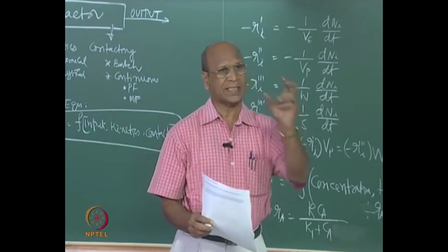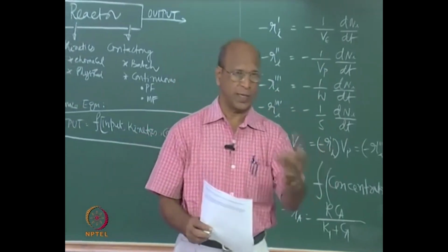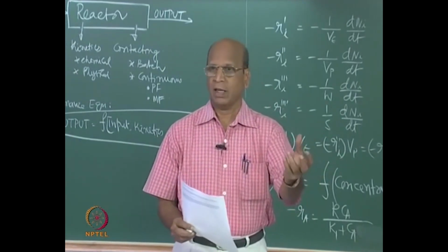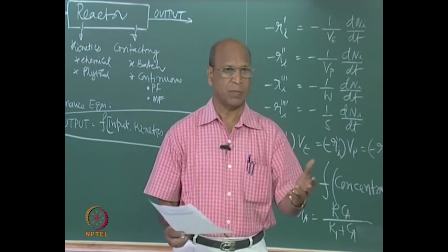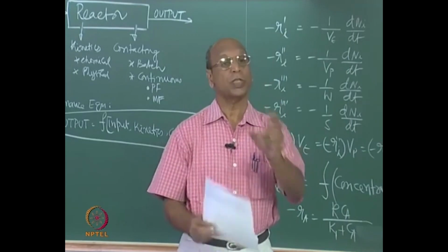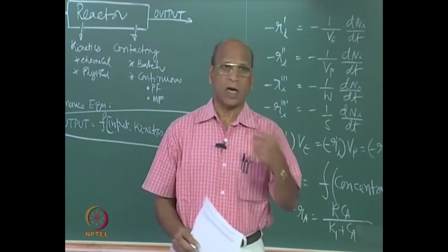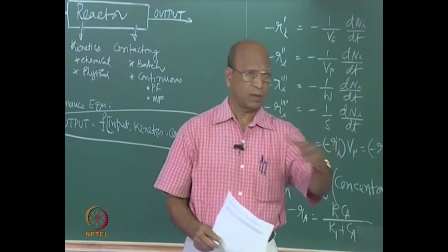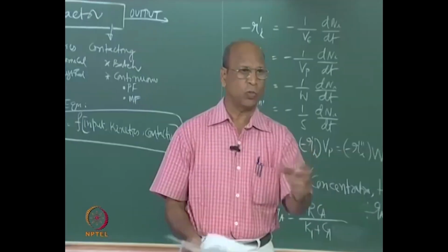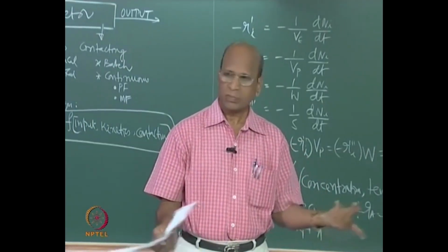So take some parameter, volume of the reaction mixture or weight of the catalyst or volume of slurry, meaning volume of solids plus liquid together, some base which is uniform for all of us. Then whether you do the same experiment in IIT Madras, Anna University, Coimbatore or Nagpur University, based on the same volume you should get exactly the same rate.